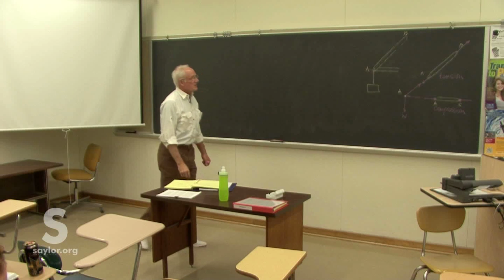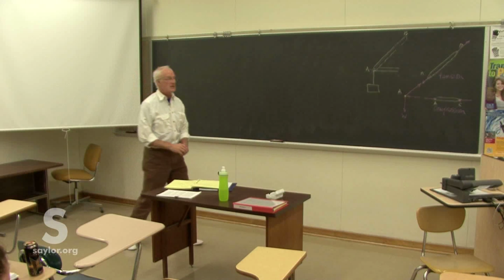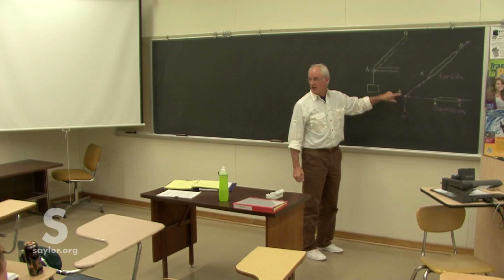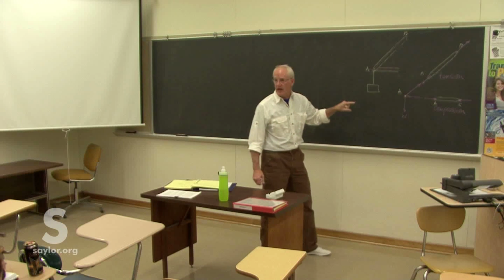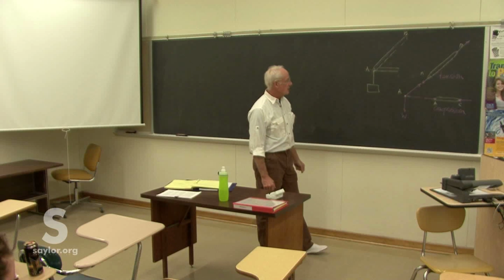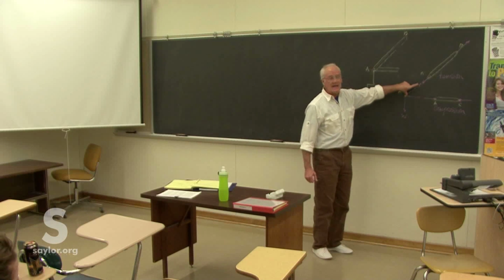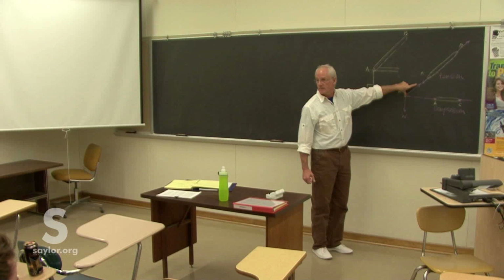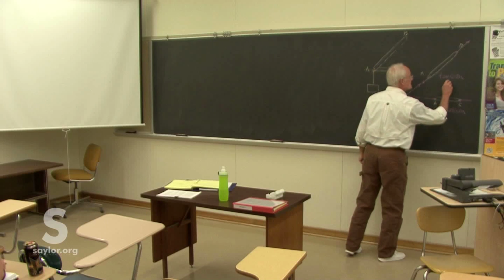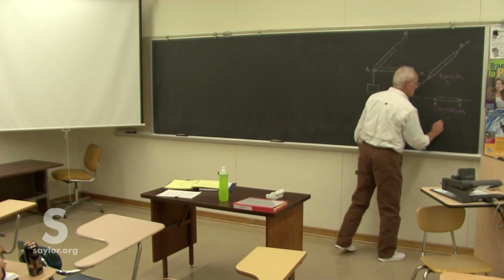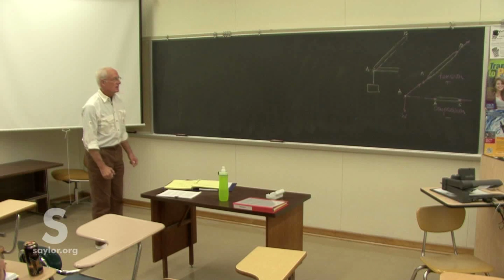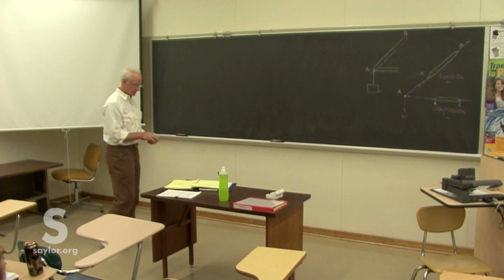So, in general, perhaps an easy thing to do is anytime there's a force and you don't know the direction of it, and you have to just take a guess, and we'll see some of those coming up in the sample problems, go ahead and guess that it's in tension. Then when you solve for it, if it's positive, you're right, it's in tension. If you're wrong, it's negative, then it's in compression. And we can use that as sort of a guideline.